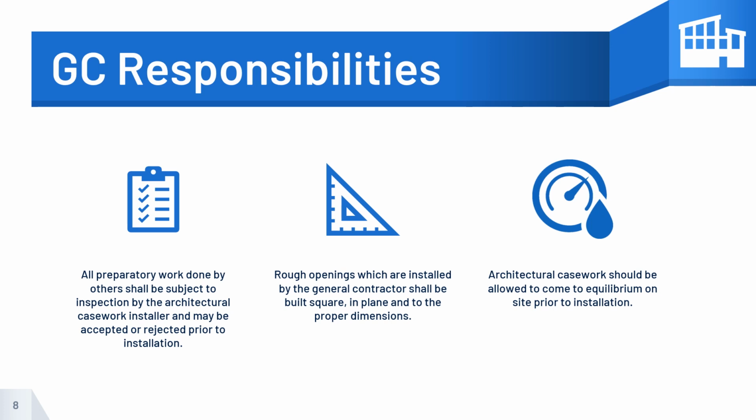Architectural casework should be allowed to come to equilibrium on site prior to installation. A minimum of 72 hours shall be allowed for best results. Factory finished casework may require a week or more to acclimate.